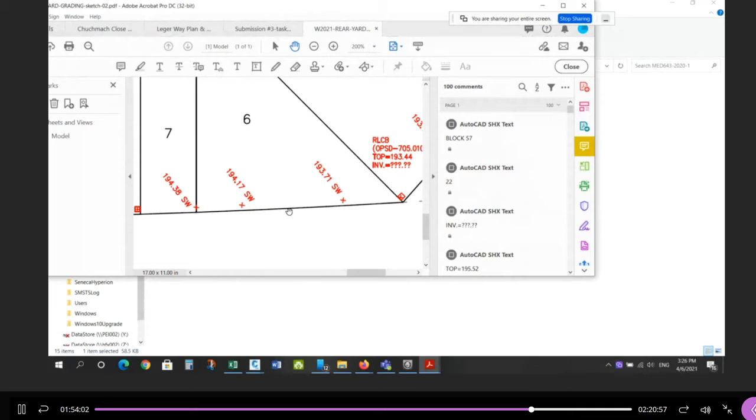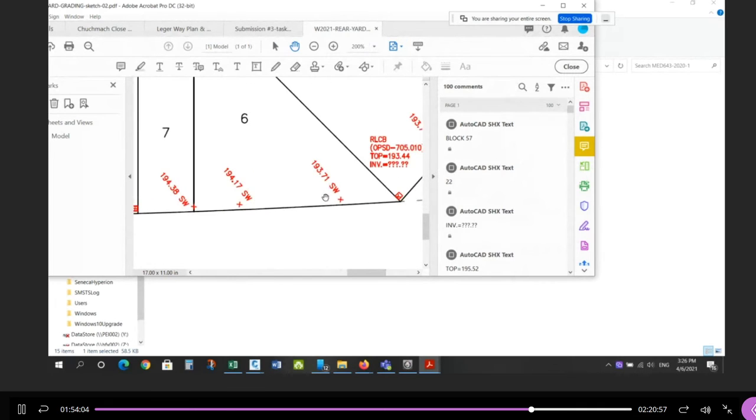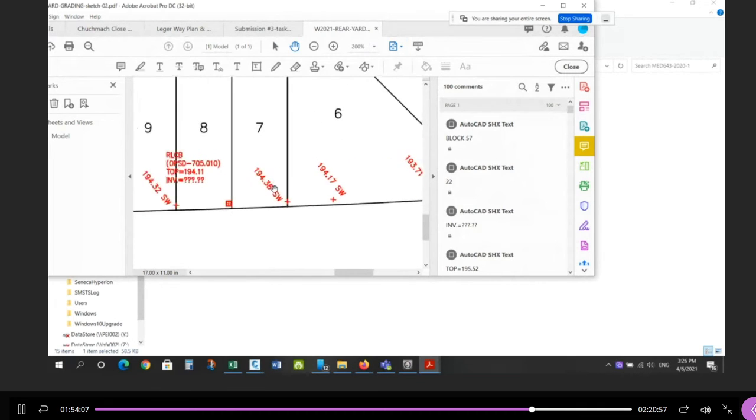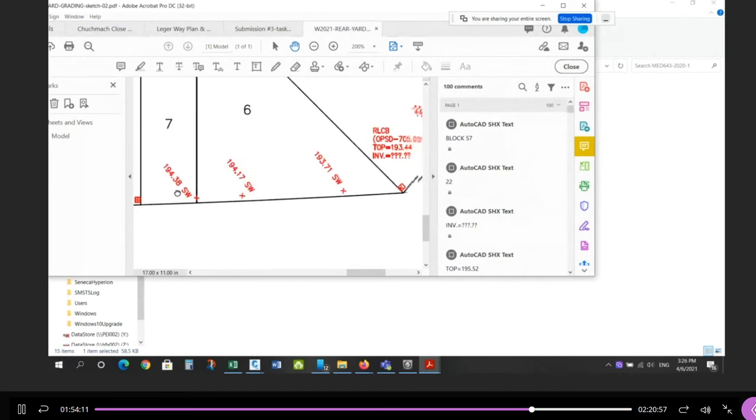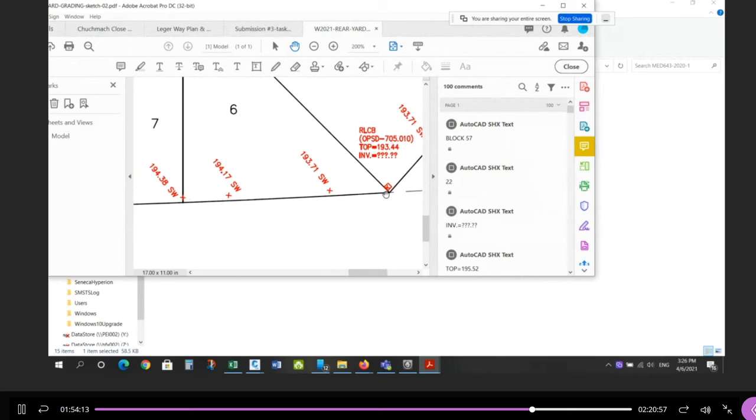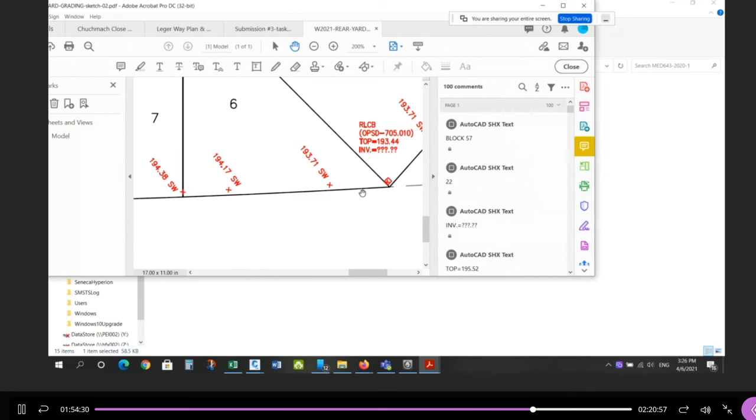Okay, those 2 points, you'll notice this is the high point. So 38 flows to 411, and then this flows all from 7 all the way to 6. So it doesn't really matter where you put them, just 2 interpolated points. If you want to calculate them, based on the rise, you can calculate the run. You know this elevation? That's the rise. You can calculate the run based on the slope between this point and this point. Okay, interpolation then. Yeah, just show me 2 points.